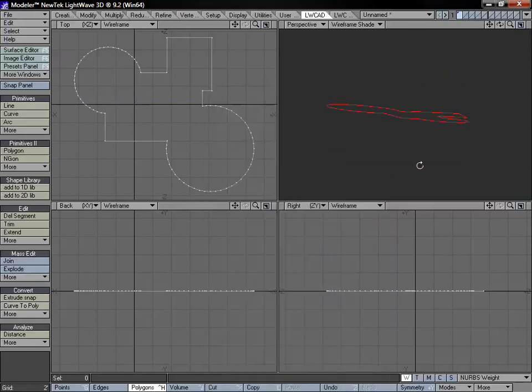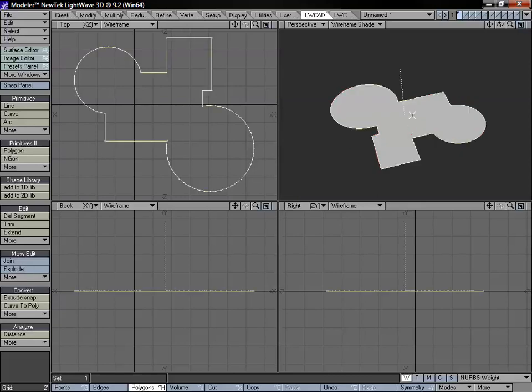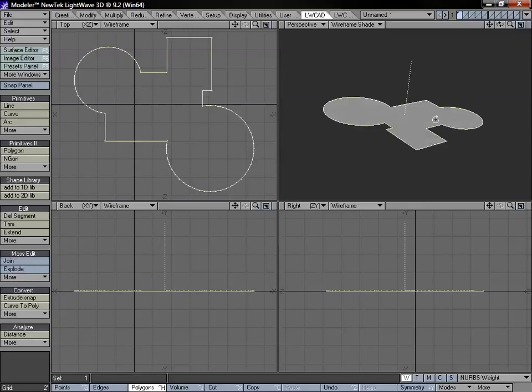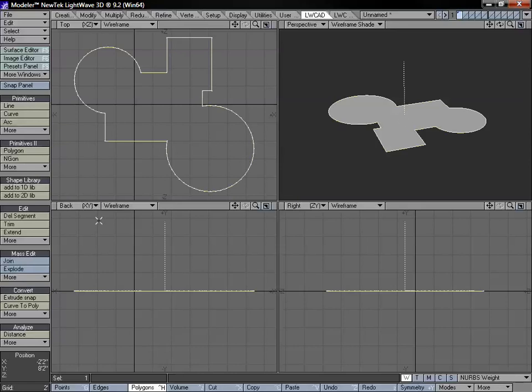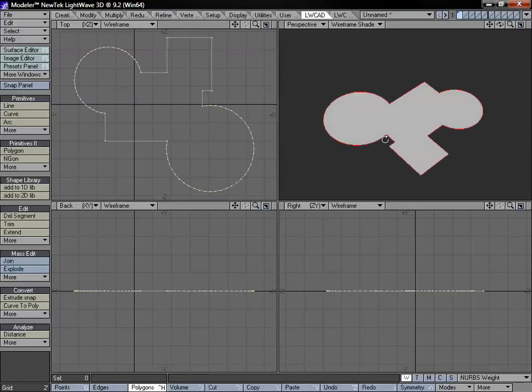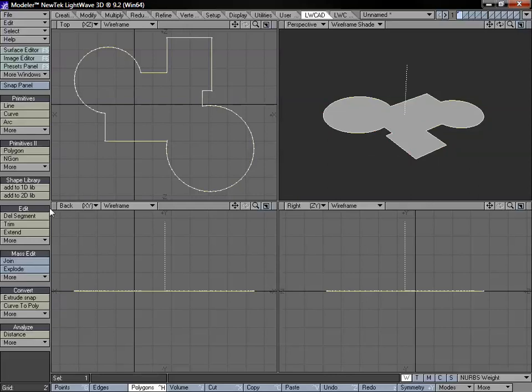So now we can see after closing, hitting spacebar, we have our object in here. And if I cut this, you can see our curve is gone because we have remove curves on. So undo. But we also notice we can still see our sketch color from our original curve on this polygon, which is nice to have that ability.